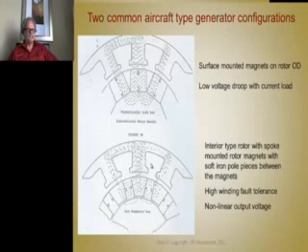But if you get a short in the windings, you'll get a very high short circuit current in the winding, so the MMF in the stator is very high, and so the flux will not take this path. It will go this way. So this is a path for the flux to go, and that reduces the flux linkage, and there's a balancing to take place.